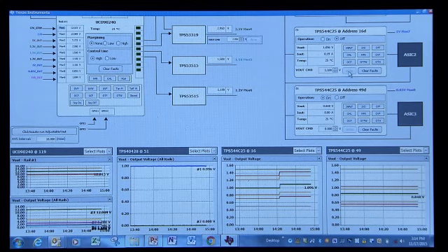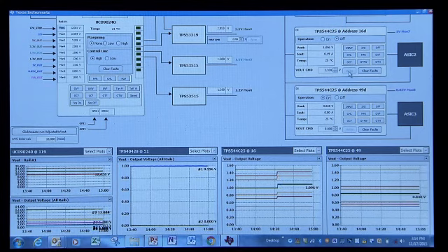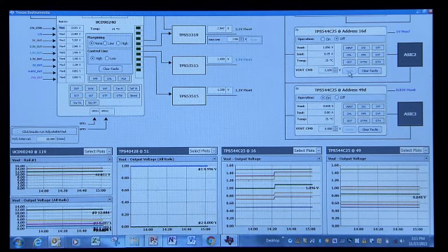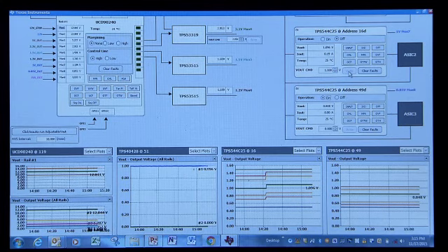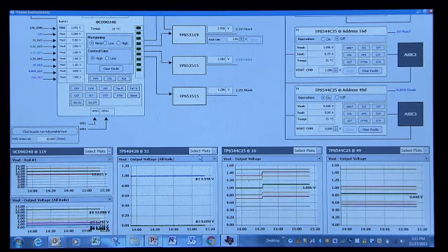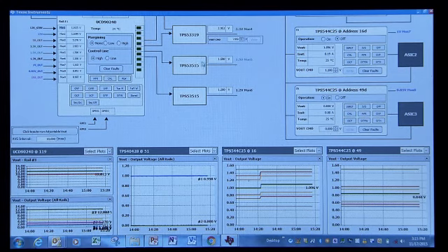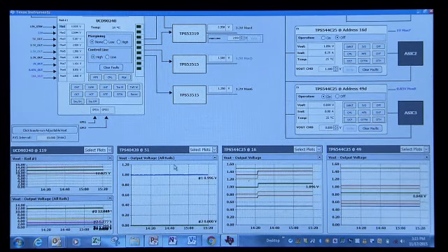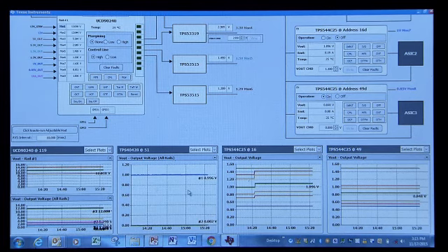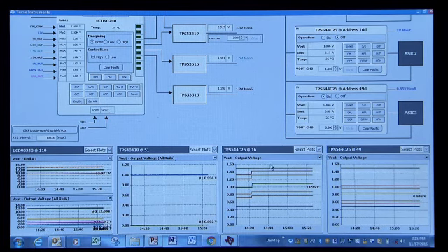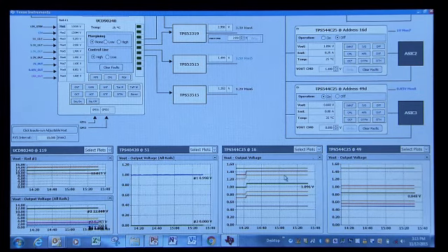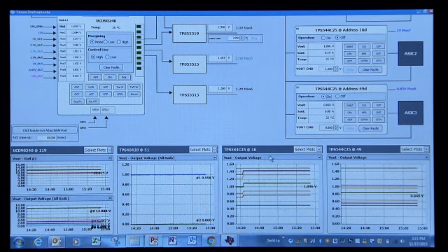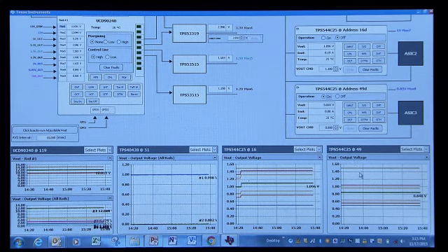So this is the TI Design PMP10896 demo board powered up with a Fusion GUI showing how the parameters that we want to measure are monitored via the Fusion GUI. So here, what you see on the left is the UCD90240 monitoring these three analog voltage regulators here, the TPS40428 monitoring its two outputs, because it's a dual buck controller, dual phase as well, and then the two individual 30 amp PMBus converters, TPS544C25, on the last two monitors on the right.